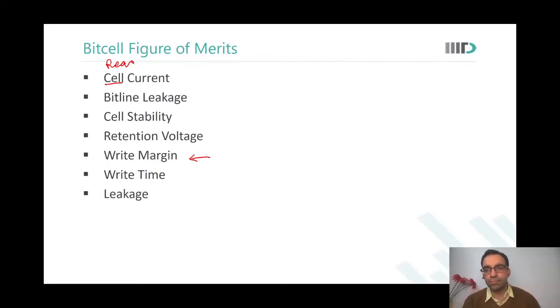Sir, in the last slide, the write cycle one, first we are reading के जो अंदर की स्लाइड से 10 है या 01 है, then we are deciding कि BLB and BL bar क्या होना चाहिए for writing purpose. No, we get the information from the user. What is D? What is the data that I need to write into the memory cell? Based on user input, I decide whether I want to discharge bit line or bit line bar. If the same data is already there and the user has also given the same data, then there will be no change in the memory content. Yeah, then the memory contents will remain same.